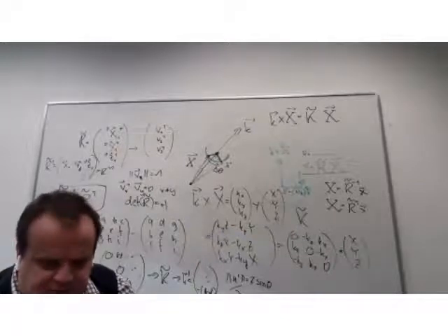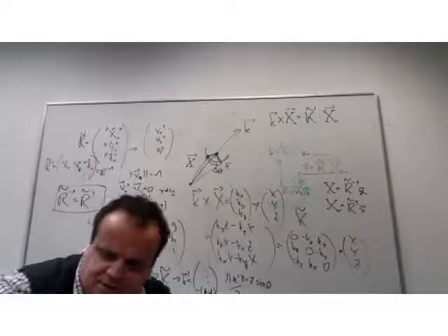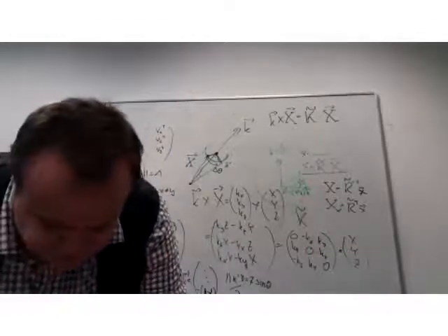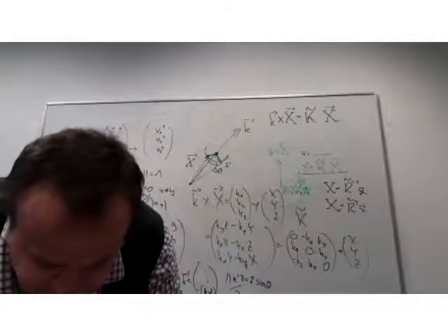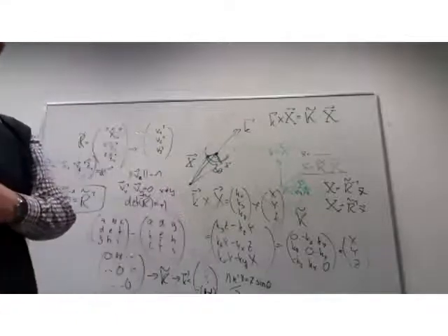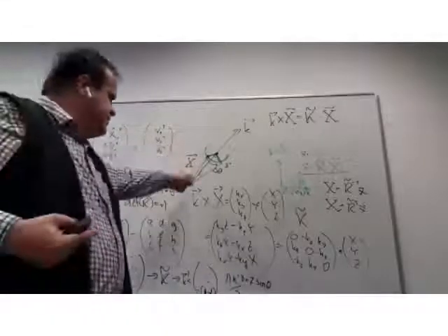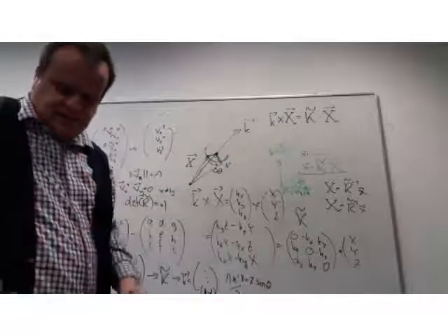Then the nice advantage is that it does not have any singularities. So the advantage of the quaternion representation is that it's compact, it does not have any singularities, and it naturally reflects what's happening in space. This is exactly what's happening because of the rotation on the axis. Our explanation with some arbitrarily chosen angles is just not the right way to go.